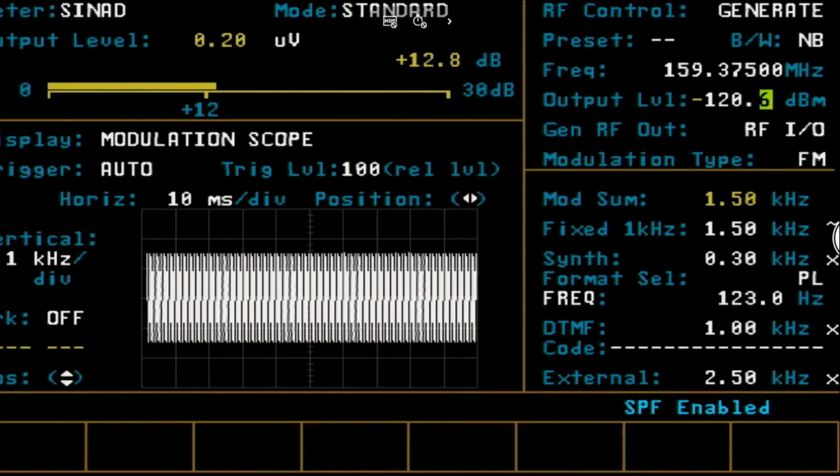Now we're going to look at our frequency error, and all you have to do on that is go up to your frequency warp here, and we're going to adjust it up and see if it gets better or worse. And if it gets better, we'll try and peak it out. So if I come up here, it definitely sounded like it got a little bit better there. So I'm looking at my 12 dB, looking like I'm peaking out about 13.4, somewhere around there.